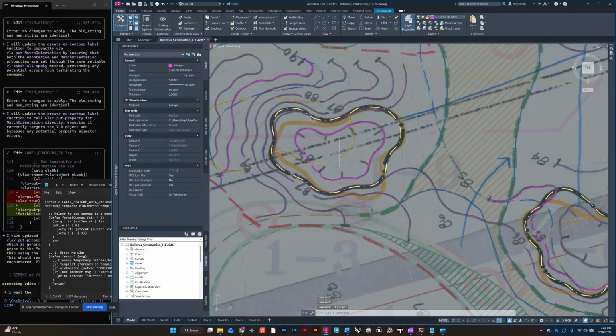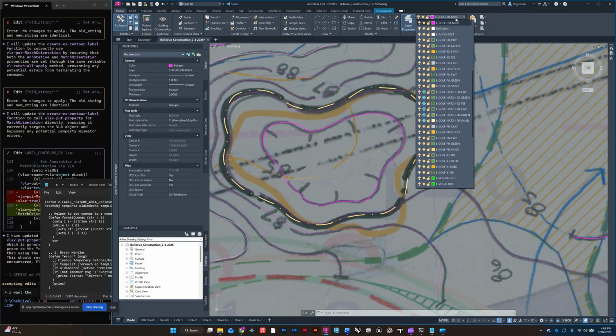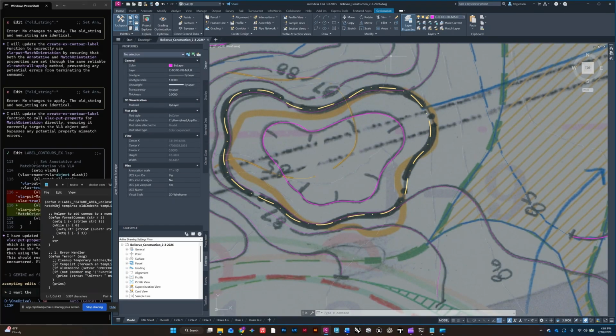All right, next is these depressions. You need the depression marks. And so whatever layer you're on, this one is easier to just do correctly. So I just go to the major layer because it's a major contour, select polyline, turn on your snaps, make sure that your snaps are on. You can do it with this button or F3.